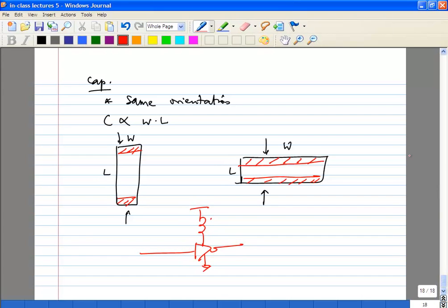Let's just take some inductance in the supply, and let's say your input is a clock. What is your output going to look like if you have some inductance in the supply? First of all, this inverter is going to draw switching current, right? Every time it switches, it's going to try to draw some pulse of current. The inductor doesn't like changes in current. You're going to get L dI by dt drops. I assume you have seen this before in other courses, right?